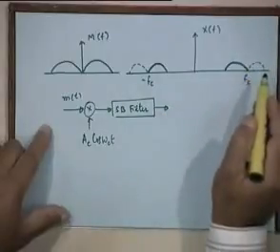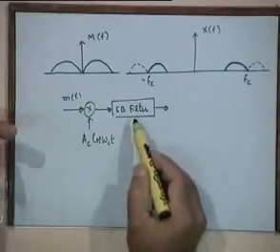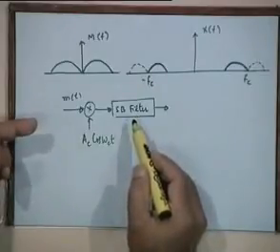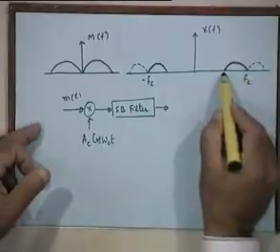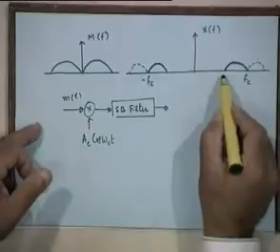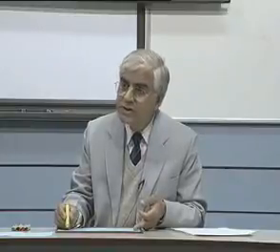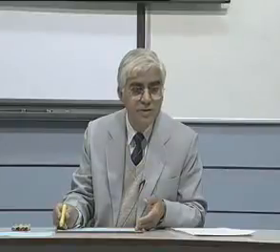If you eliminate the upper sideband, you are transmitting the lower sideband, and for eliminating the upper sideband, you can use a low pass filter or a band pass filter whose pass band is from f_c to f_c minus B, right. If you want to transmit the upper sideband, you have to use a high pass filter or a band pass filter whose transfer function is non-zero between f_c to f_c plus B, right. So, that's how you will choose a sideband filter.